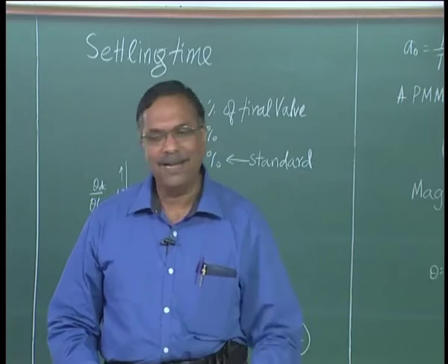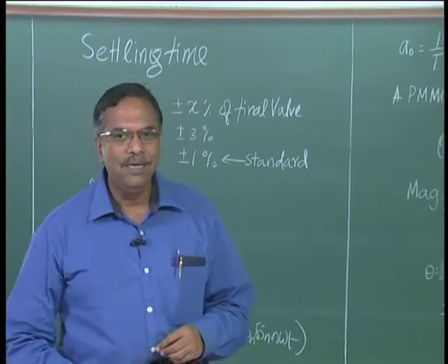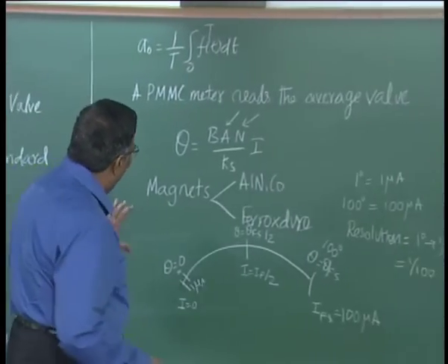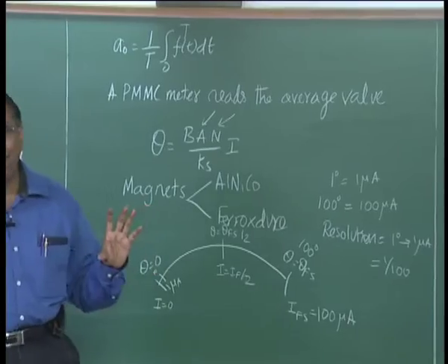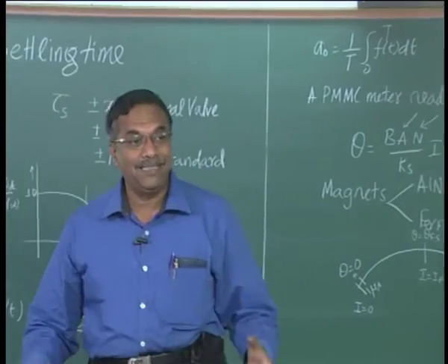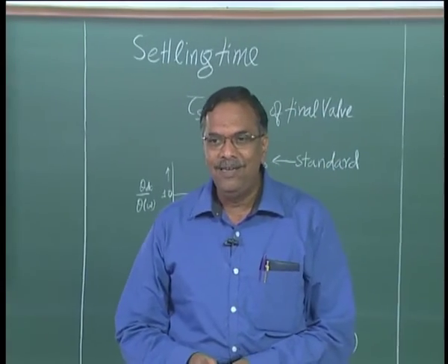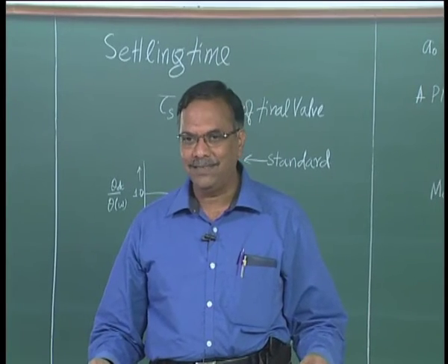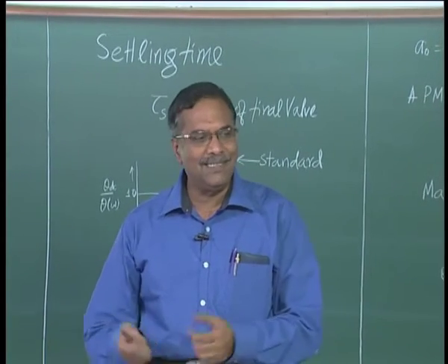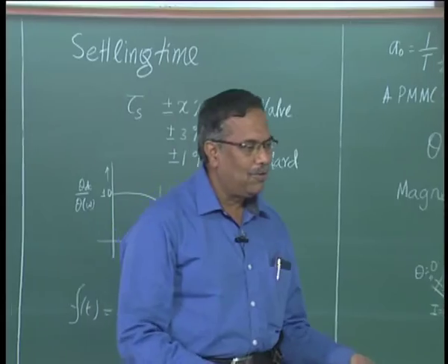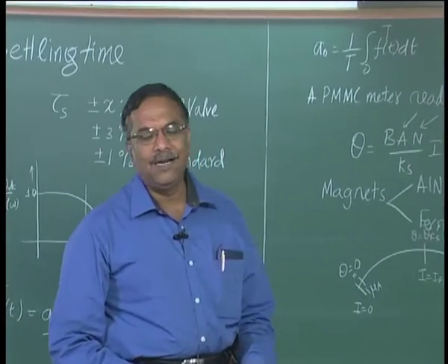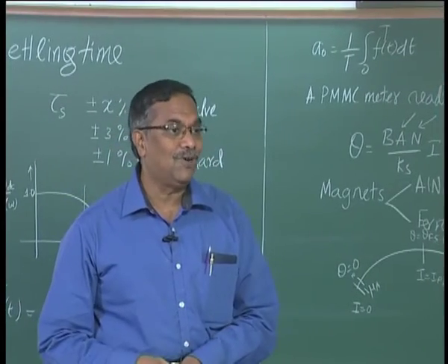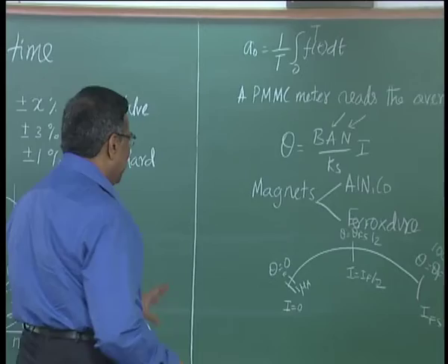First meter, one magnet he will put, second meter he will put another, but these magnets, however hard you try, when you manufacture let us say 1000 magnets, each one will have a different value of remnant flux density. One may have 0.76 Tesla, the other one could go down to 0.7 Tesla, the third one could be 0.85 Tesla, and so on. So there would be a variation.